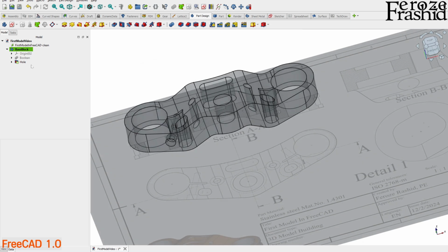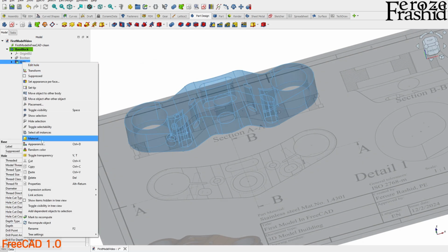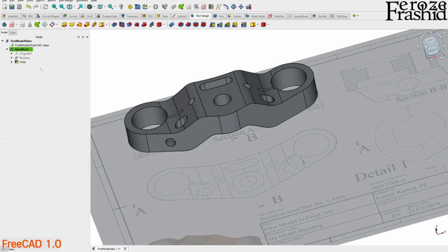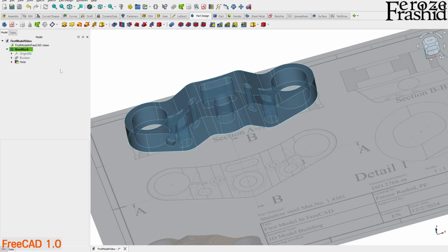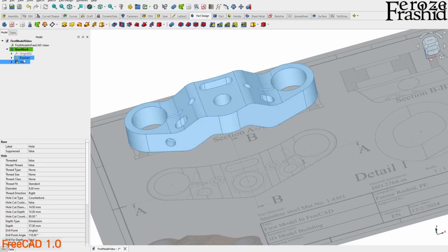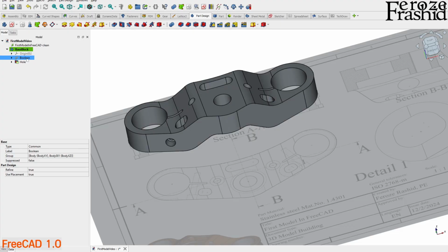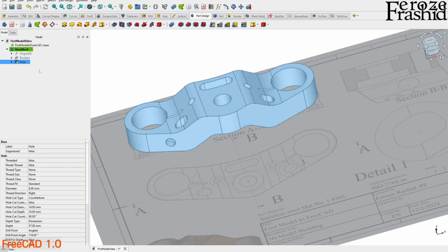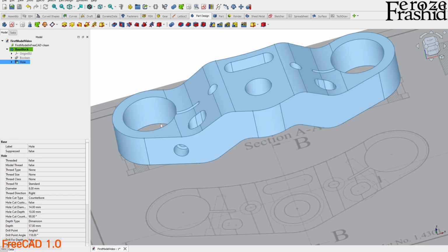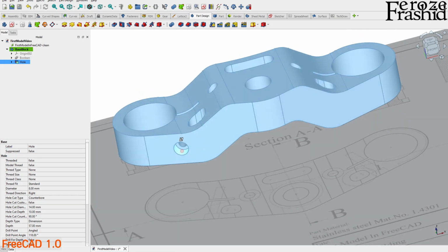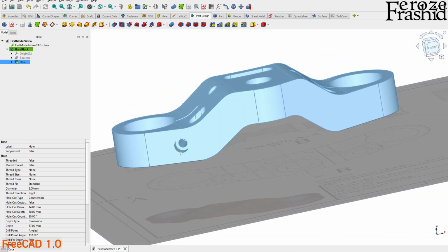Now at this moment, let's think about it. Previously, when we created two sketches and then two bodies, those bodies were selectable separately. We could select two bodies separately and then make that intersection in a Boolean operation. But on top of that we built another feature, the hole here, and we didn't have to do any kind of Boolean. It just integrated, it cut it out by default.